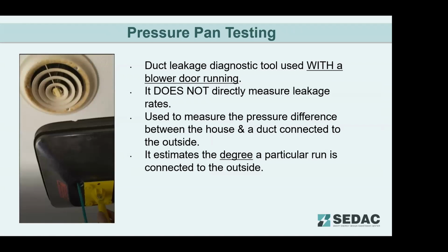And the pressure pan testing, generally, you're going to be using this test primarily for testing how leaky a duct is that's in an unconditioned space. So the pressure pan is in the picture, and then there's a supply register in the ceiling. That supply duct is in the attic.